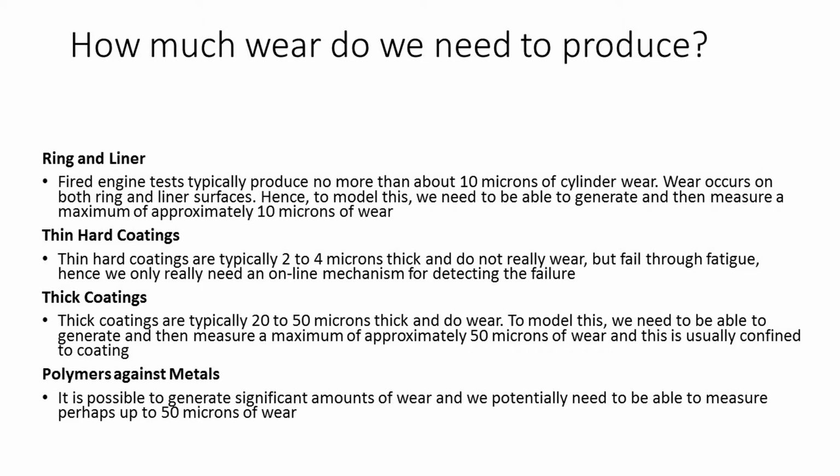Thin, hard coatings are typically 2 to 4 microns thick and do not really wear, but fail through fatigue. Hence, we only really need an online mechanism for detecting that failure. The failure is confined to the coating, and there is no point running on the test once the coating has failed. No one is interested in the frictional wear of the substrate. It's important to ensure that tests run on the coating, not the substrate.